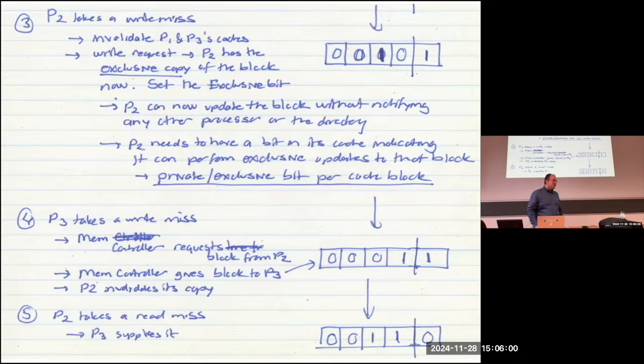But then the question is, do you need to make 1,000 processors coherent? You may not want that, right? You can also think about clustering your chip and trying to be coherent in every cluster. And then when you allocate your program, you don't allocate to all the clusters. You only allocate to those partitions that are coherent. But if you want to keep 1,000 processors coherent, it's not really easy.